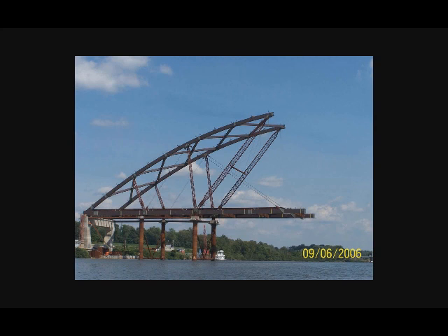So here the bridge is erected. This was done by barge construction. They came up with this erection scheme. Actually, the guy who came up with it unfortunately passed away. He was a high school dropout, but he built like 10 of these arches all over the Ohio River. So you can see a nice system. You see the arch rib supports, you see the struts that support the arch ribs, and then you can see the cables that support the cantilevering part of the tie girder.